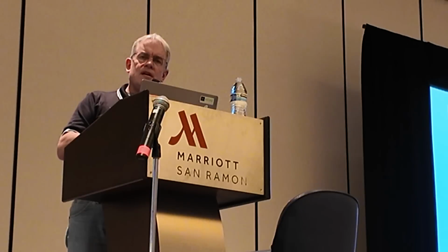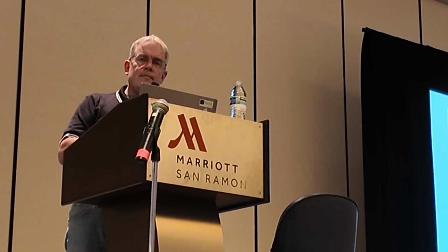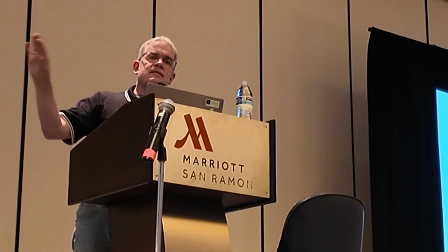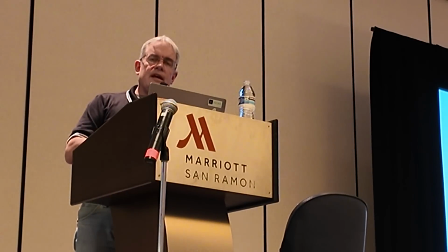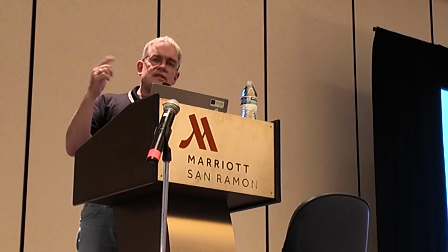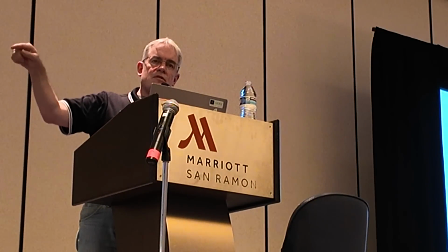I think so, because I have an IntelliTuner MFJ 200 watt tuner. Yep. And then this would go above that or whatever. You want the tuner outside the loop. Tuner outside the loop. Yeah, okay. So this would go before that. You'd put the sampler before the tuner, then you'd have the tuner, then the antenna.